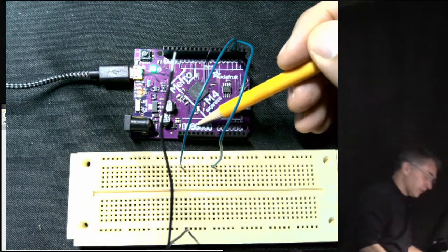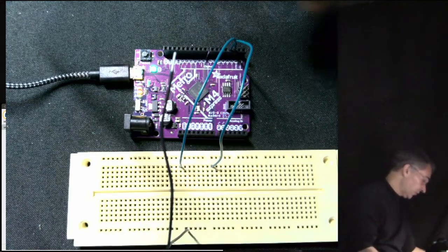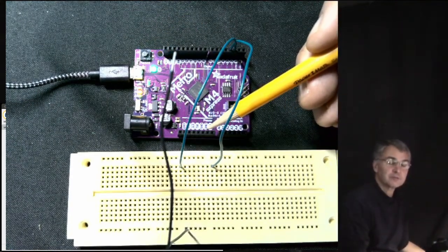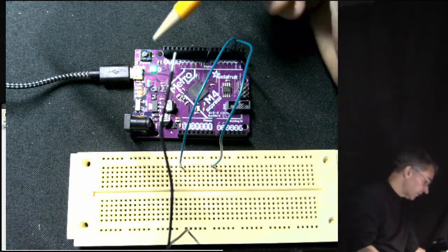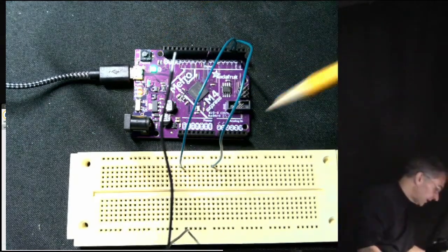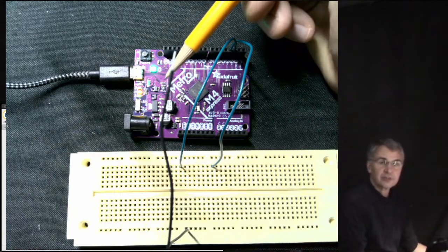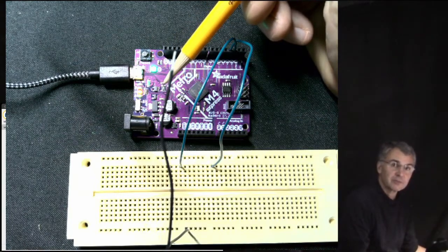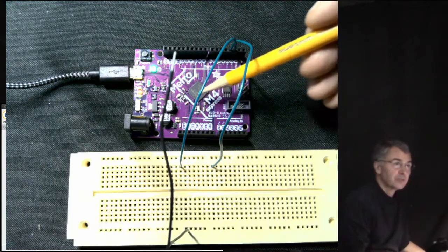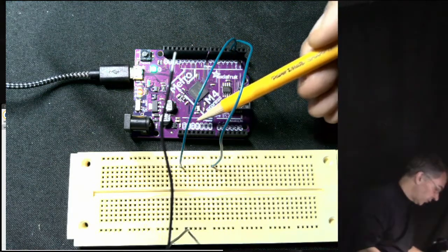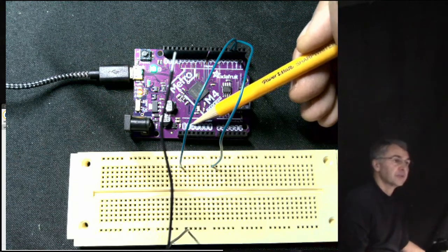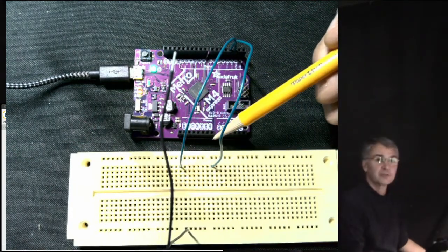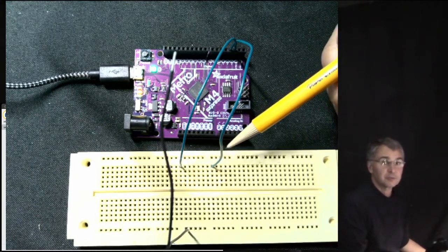So then this is 5 volts. The 5 volts comes from the USB connector in this case. So it turns out most USB devices run on 5 volts. So this little board gets 5 volts from the USB connector. And then on this board, it uses a clever device called a voltage regulator to produce 3.3 volts, which is the voltage that powers this chip, which is the brains of the board and everything else on the board. So when I say this voltage is 3.3 volts, I mean that if you were to measure between here and ground, you would see a voltage difference, a potential difference of 3.3 volts.